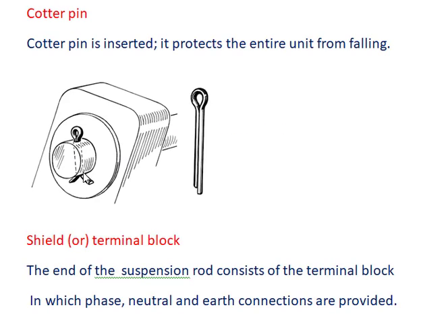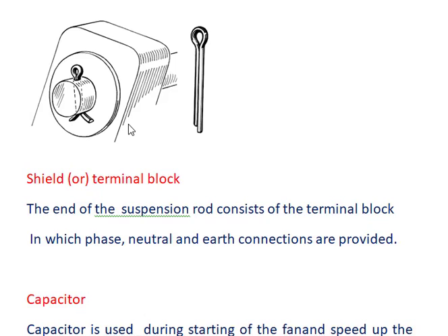This cotter pin is inserted here and the two legs are bent like this. So this unit cannot be moved here. So it is used to protect the entire unit from falling.